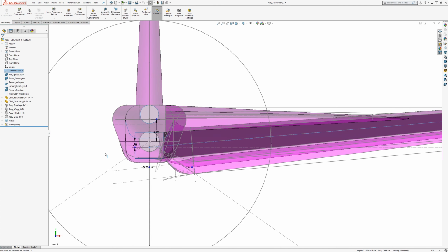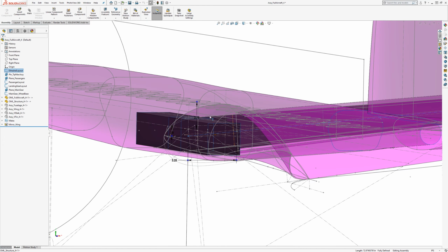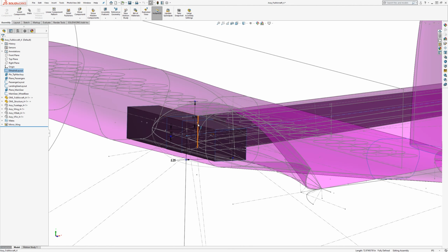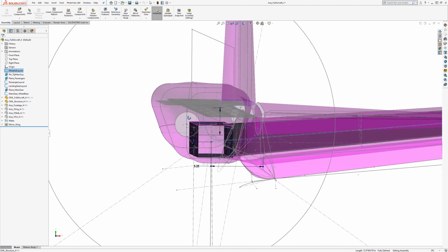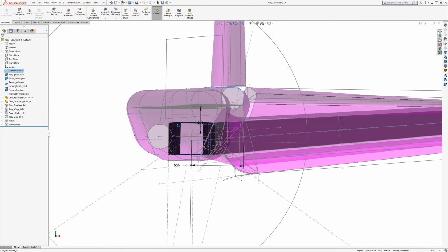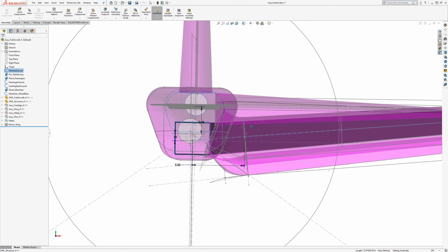And well, yeah, the intention here was for it to meet in the keel beam that could house payload just underneath all the passengers. That was the intention here, for the wing box to meet this keel beam in a way that the loads kind of intersect all at the same point in here.